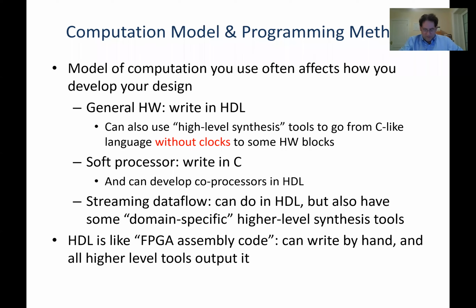And high-level synthesis tools go from usually a C-like language, doesn't have to be C-like, but C-like is the most common one, to hardware blocks. So their output is normally HDL. So they basically go from a higher level description to HDL. The key distinction is that HDL has clocks and high-level synthesis does not have clocks, okay? Because HDL doesn't describe every detail of your hardware either.